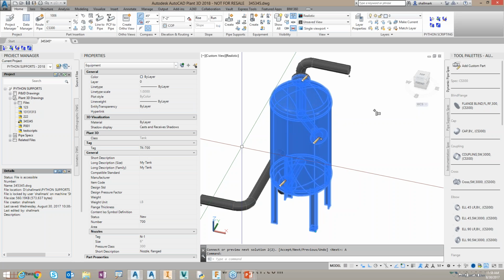Another question here. The ADSK model updates in Plant when the file changes, but the IAM does not. I think I understand what you're saying now. If this is dealing with the same thing, no. If we insert that exact same ADSK in, we're not replacing an existing one, so it doesn't just do a refresh over the same file.